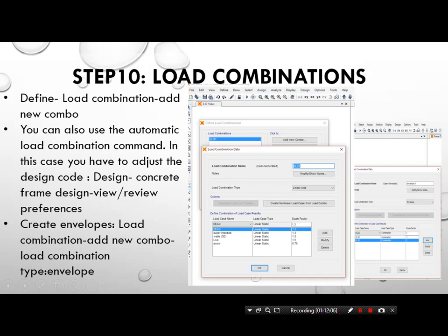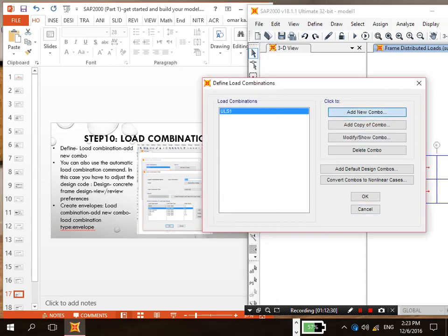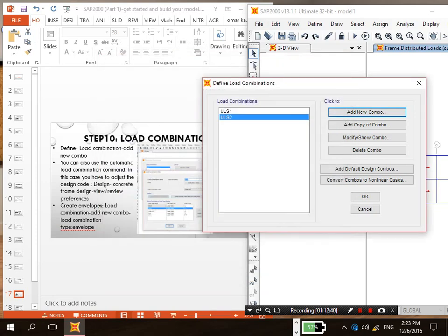Okay. Let's say sometimes you have different cases. In order to have, for example, the maximum shear, you have to assign maximum load on both sides of the column. So if you would like to have your critical case, you have to do different cases. And this way you will have different combinations. So let's say you go in this way, you have to define another one as ULS2, and here some loads, etc. So then you will have different cases here. Okay, you got the idea.